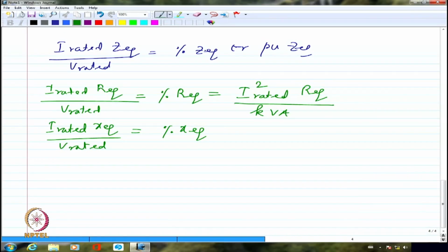See, if I am calculating separately for the primary and separately for the secondary, and trying to write Kirchhoff's laws, how will I take that into consideration? What I have to do is write two loop equations and step up or step down the voltages and currents every now and then. I wanted to represent the whole thing as one single electrical circuit, if possible, which will give me ease of calculation.